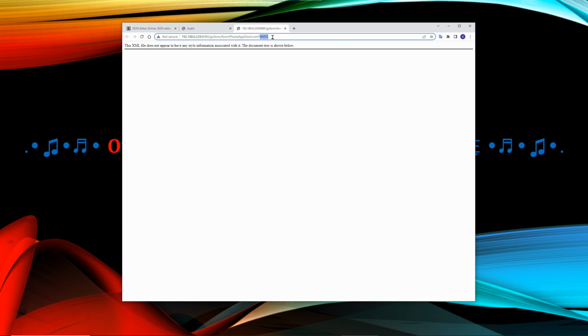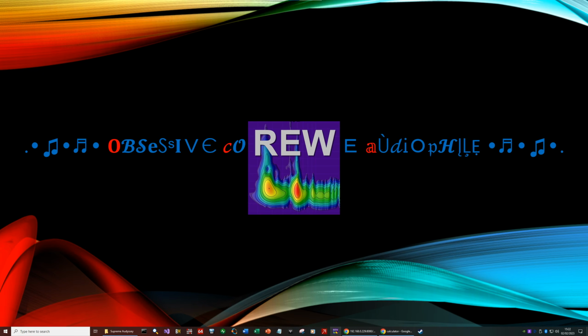Also, don't forget to set your subwoofer power settings to permanently on, not auto, during calibration. It happened a couple of times to me that when I'm measuring a speaker with crossover active, one of the subwoofers switched to standby mode and you only measure with one subwoofer. Bass response is wrong. It can become very confusing. Better set them on during the calibration. Now it's measurement time.